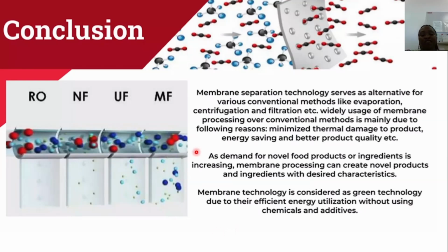Our conclusion is that membrane separation technology serves as an alternative to various conventional methods like evaporation, where you are removing minerals from water, and processes such as centrifugation and other filtration processes that are widely used in processing. It is preferred over conventional methods mainly for the following reasons: we have minimized thermal damage, energy saving, and also better product quality.